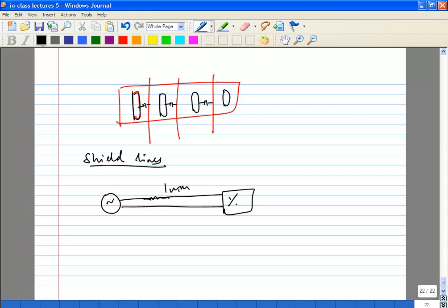Okay, but what happens if you make it wide? Obviously, you'll have some extra capacitance, and you have to be careful because if you add too much capacitance, then you'll be burning a lot of power trying to drive it. Okay, so at the end of the day, if you look around at these RC values, there will be a certain optimum resistance and capacitance, and an optimum power. So obviously there will be an optimum width.